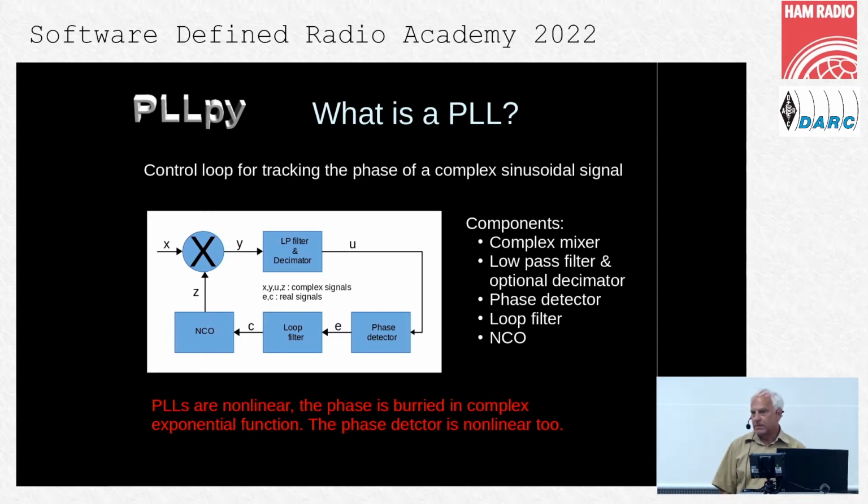In the first part of this presentation, I will talk to you about the behaviors and the features of software PLL. In this slide, you see the block diagram. The PLLs are essentially control loops which track the phase embedded in a complex exponential function.